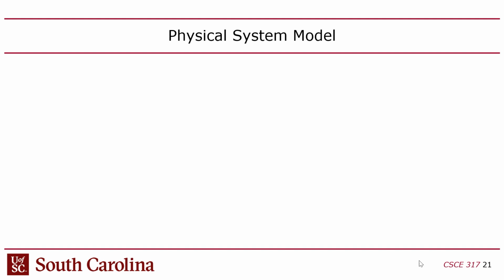It's going to hit a limit, right? So even then, you're not going to see an infinite explosion, right? You're going to hit some kind of limit because real controllers are nonlinear, and we're imagining everything in this case as a linear system. So in a purely linear system, you would get this infinite growth in an unstable system, but in practice you can't, right? Does that make sense? But you still have to make sure your controller and plant combo are stable.